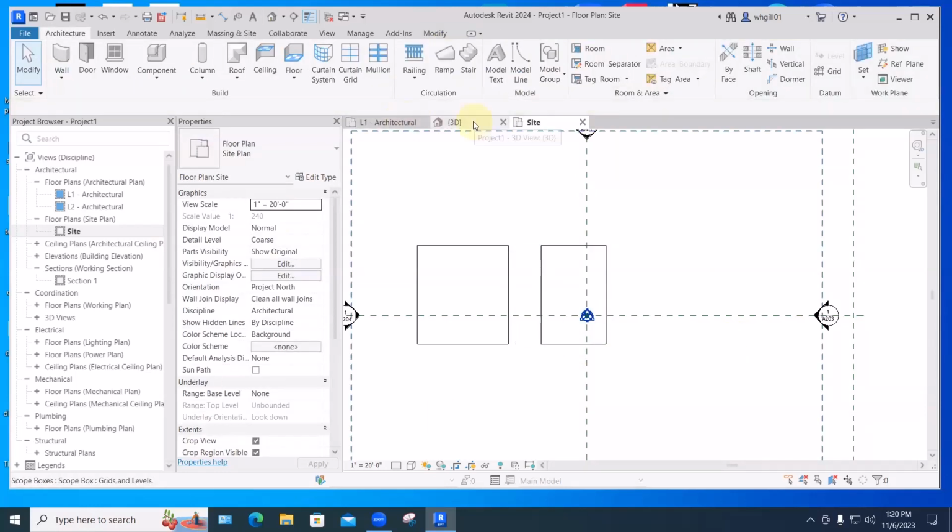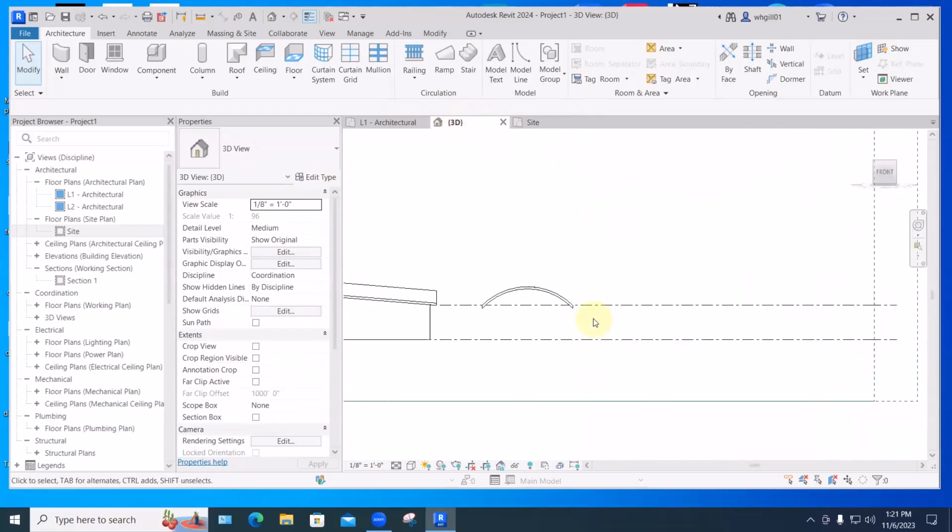What we need to do here is go back into my front view. And if you remember when we drew the tapered leg of the coffee table, it started out circular, got bigger and turned into a square by the time it got to the top. That's a blend from one shape to another. I'm going to be doing a blend from one curved shape we're seeing in plan this way, the bottom of it, to another curved shape in plan that's up higher. So then Revit will extend it up. We'll just show you how this works. See if I get it right this time.